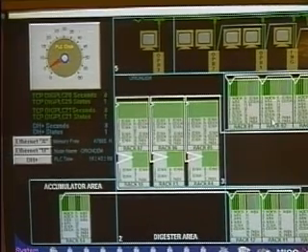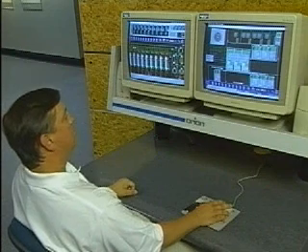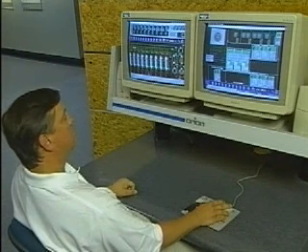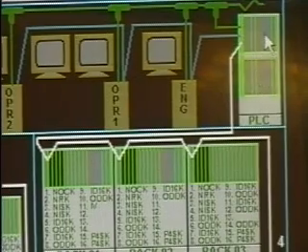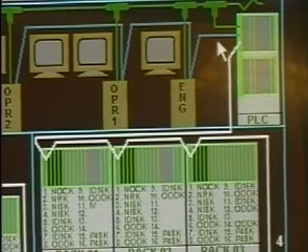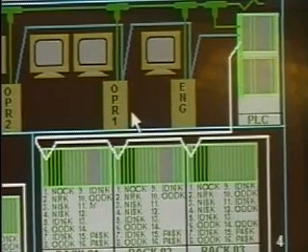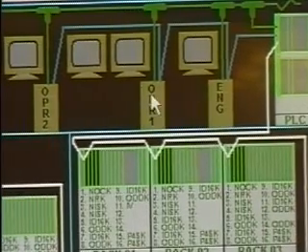We have used a combination of commercially available programmable logic controllers and Intel workstation technology. It's important to realize that this is a fully redundant system. We have two Allen-Bradley PLC-5/80E PLCs in a redundant configuration, redundant highway connections, one Ethernet connection, and a Data Highway Plus connection going throughout the system.